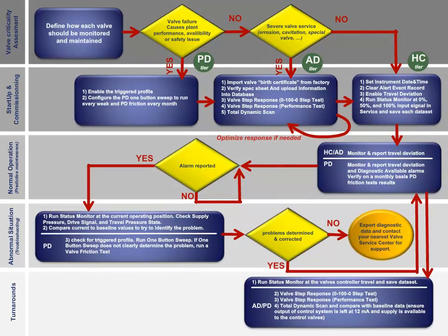1. Run status monitor at the valve's controlled travel and save dataset. If instrument is AD or PD, then 2. Valve step response, full stroke. 3. Valve step response, performance test. 4. Total dynamic scan and compare with baseline data.